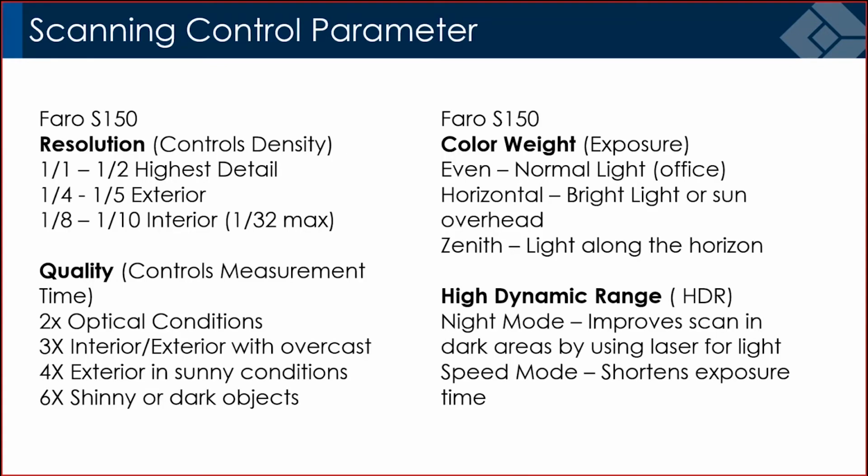Okay, so again, getting a little deep in the weeds here, but I do want us to understand this. This page is meant to explain some of the control parameters of our scanners. Based on the desired accuracy, the time of day, on-site conditions, and the time that we have to scan out in the field, these settings will help us fine-tune how the scan is performed in a timely manner, and get the amount of data that we need for the needs of the client or internally.